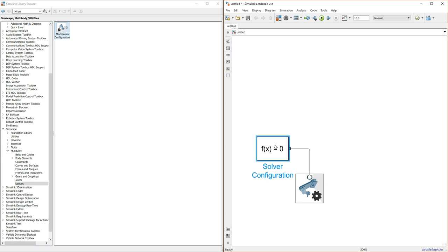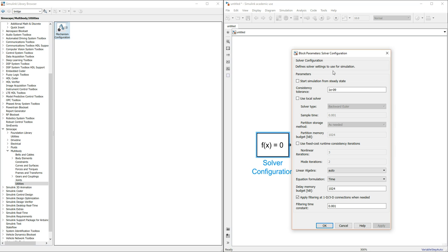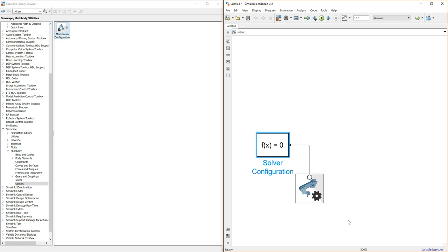We just had a little bit of an introduction through the actual block itself. Finally, we know where gravity is. We know how we're going to solve it. We know our relative tolerances. If I go into the solver, we know that it's going to be using the backward Euler methodology. A lot of people will always claim that Runge-Kutta will be the best way in this case, but funnily enough, a localized solver of a backward Euler is actually a little bit better in this case.